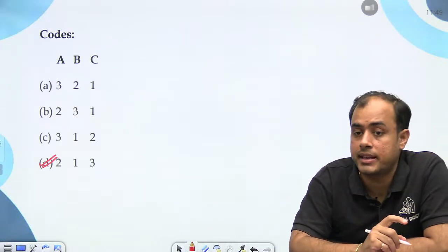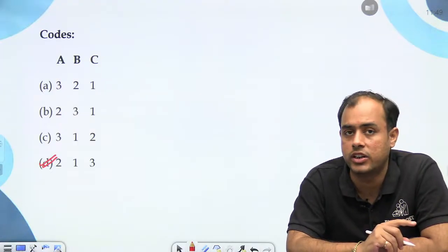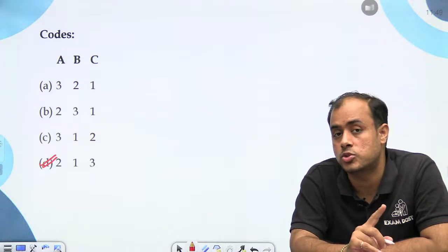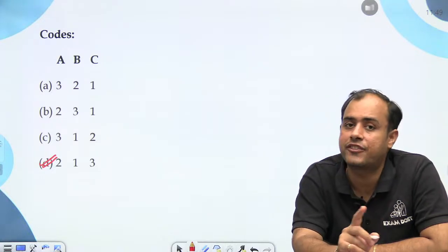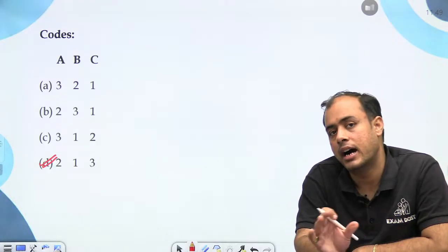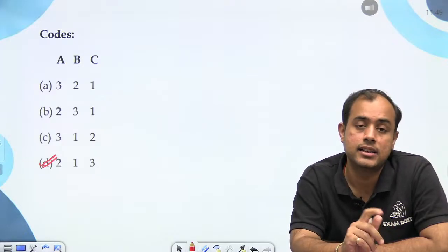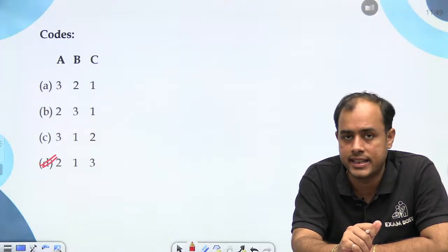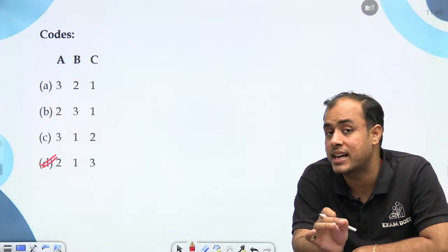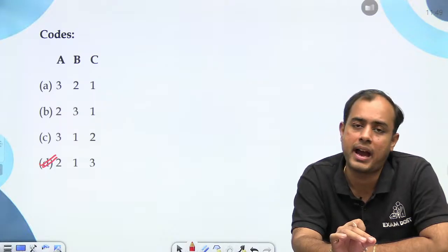Back to back connection is basically used to connect two systems having different frequency. Suppose I have a system operating at 50 hertz, another system operating at 60 hertz. They cannot be directly connected, so they will be connected with the help of a DC link. So when two systems operating at different frequency are lying at the same location, the link of HVDC is called back-to-back link.